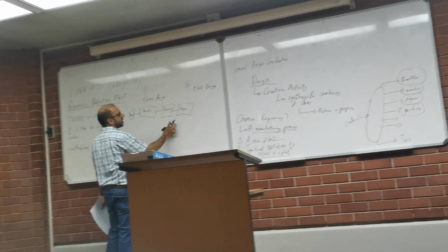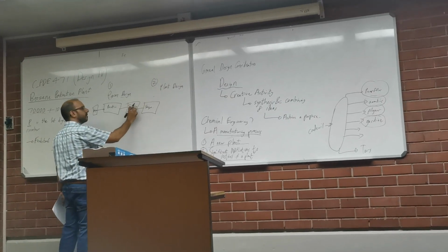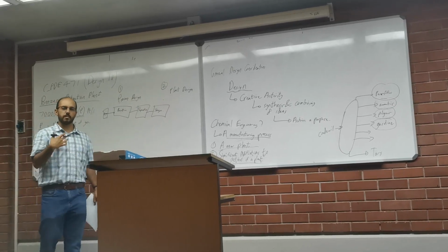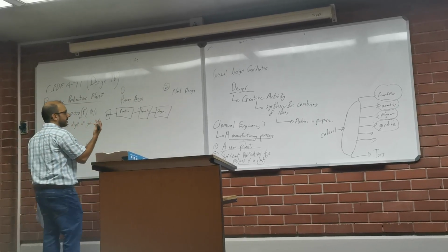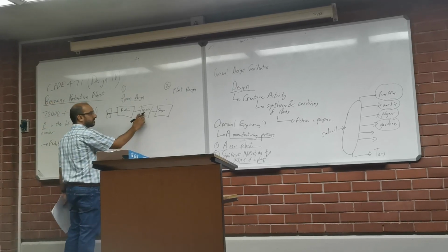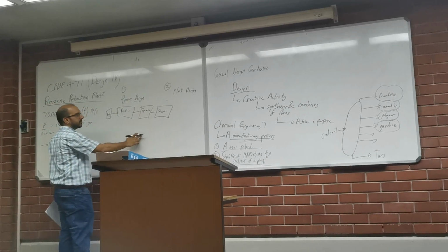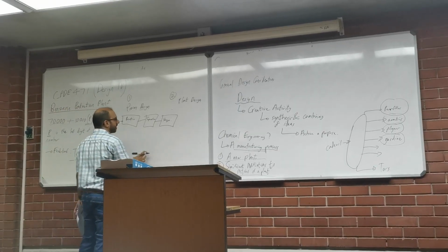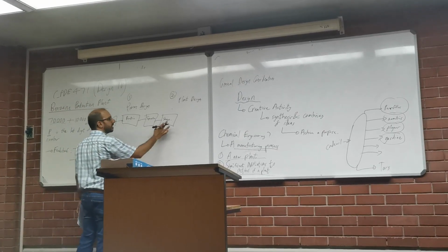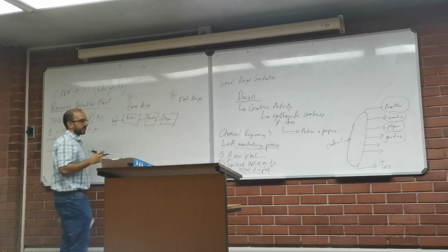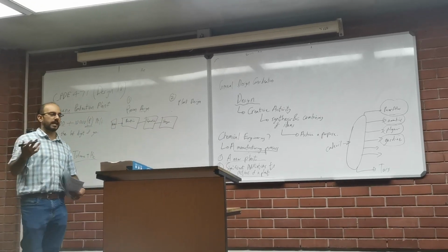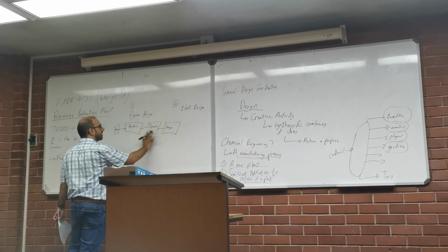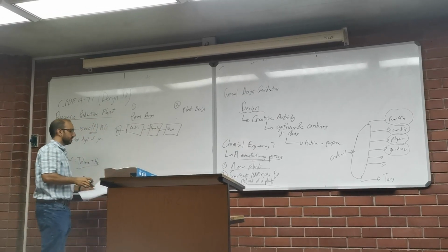Then on your separations, there's various separation routes: distillation, absorption, stripping, membrane filtration, liquid extraction. So various types of separation processes that you need to research as an engineer. And then of course there is storage. Storage tank design is relatively easy compared to your core process here, reactions and separations.